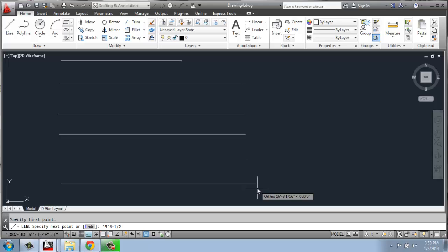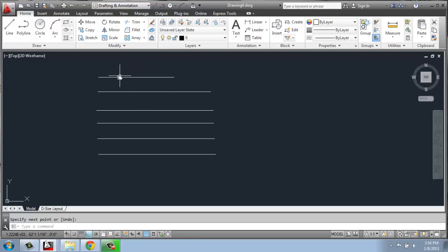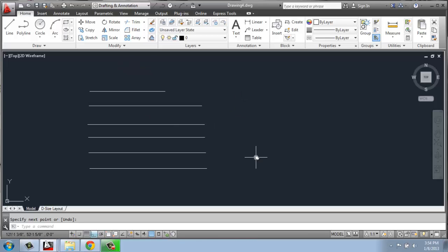If you want to type in fractions of an inch, you have to put in that little hyphen right here, because hitting the space bar is the same as hitting enter, so you can't put a space in there. So when I hit enter, you'll see that that's the measurement that I created. Okay, so it's all about getting more and more specific as we're moving down here.